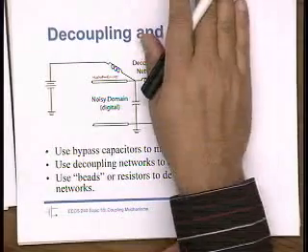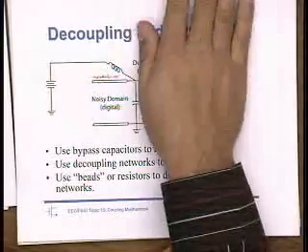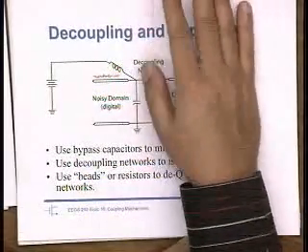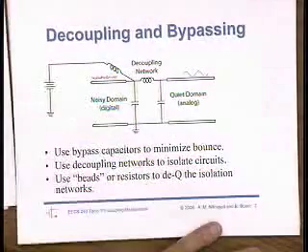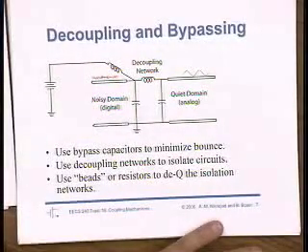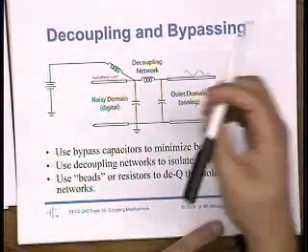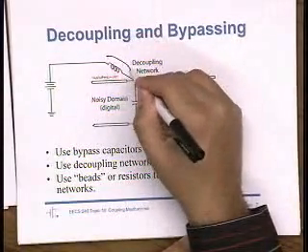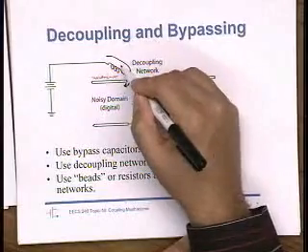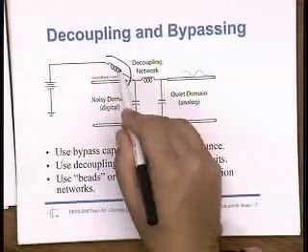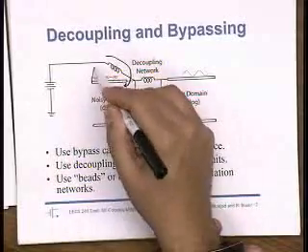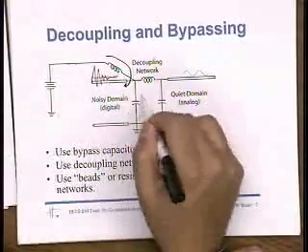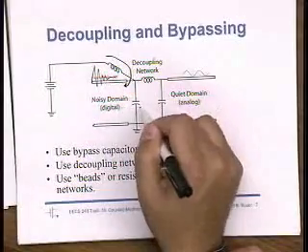Let's just forget about the rest of the circuit. Let's just talk about the digital side. So the claim is if you put in this capacitor, the ripple goes down. Why is that? Without that capacitor, it's drawing its current from off chip, and that's going to have a larger inductance. Very good. So the current would have to come from here, and this inductance is even larger potentially than, let's say, the lead inductances of our board. So then the ripple would go up even higher. So this decoupling capacitor is very helpful.